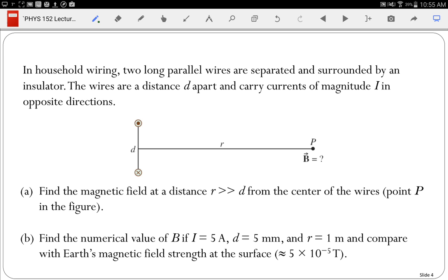But a key here is you have 60 hertz AC. You have electricity that's going back and forth in those wires 60 times per second. And so having current in a wire creates a magnetic field. Because you have those wires separated by a distance, you're going to create a magnetic field that's fluctuating with those wires. If you have another wire next to it, that fluctuating magnetic field can cause charge to move in the second wire. And so you can have interference between wires.